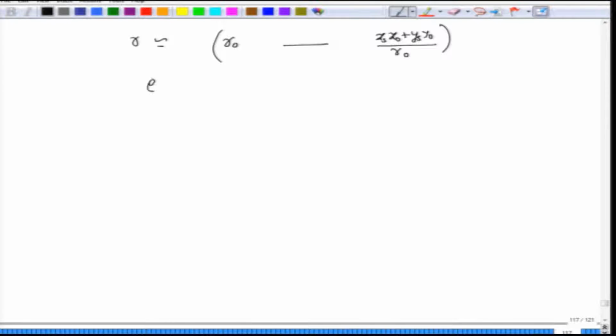So, in the denominator of e power minus j k r by r, what I can do is to further approximate the denominator as 1 over r naught, because you are making a similar approximation to what we made in antenna analysis as well, right. There also we had an e power minus j k r, and in the denominator we had an r. There we made this kind of assumption. This assumption is sometimes called the paraxial assumption, especially in the context of diffraction, and that is what we are actually making now. We assume that this is 1 by r naught in the denominator, and in the numerator we will write down this approximation. Okay. So, I can't make the approximation in the numerator that r is equal to r naught.